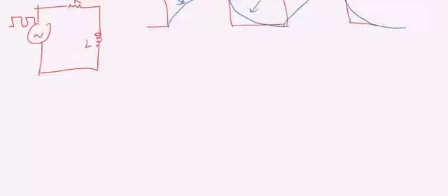The only difference is that tau, the time constant, is going to be L over R. So again, remember the tau for the RC circuit was R times C. Here the tau is L over R. This means that if the resistor is a big resistor, the tau is going to be smaller here, and if the inductor is a big inductor, the tau is going to be a large tau.